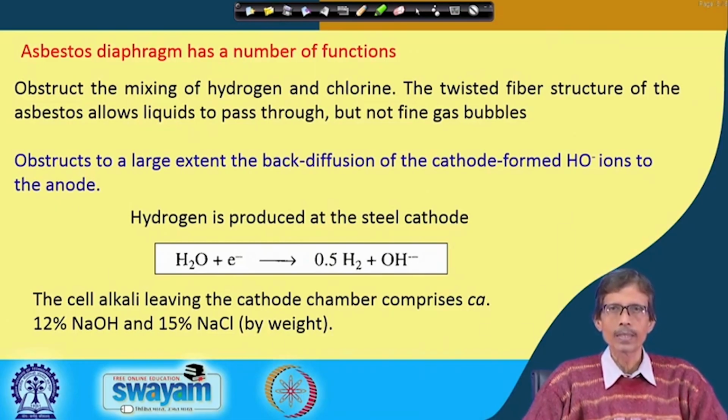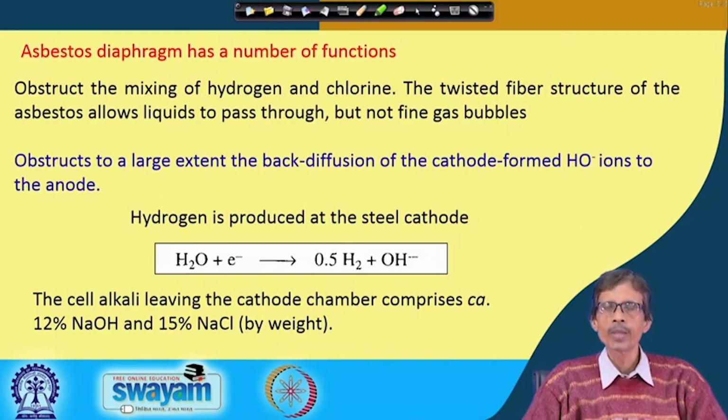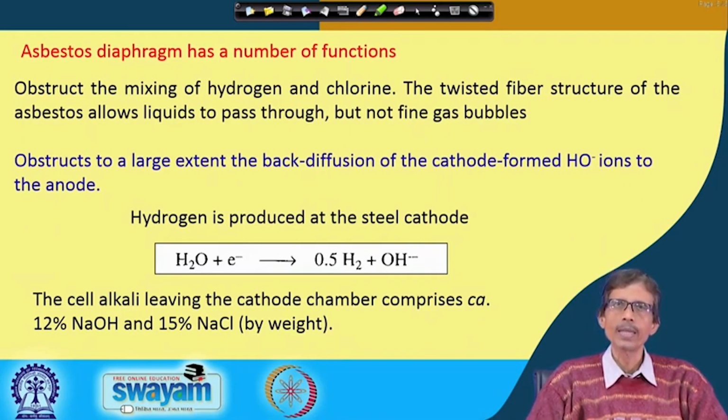Because of the partial or selective crystallization of these two, when you take these two quantities out from solution, they are solid. So, solid cakes of sodium hydroxide and solid cakes of sodium chloride can be produced from there, and you can separate these two, because fractional crystallization will allow one of the materials to precipitate or crystallize first before the other. So, the separation through crystallization is possible, and you get two solid products out of this reaction chamber.